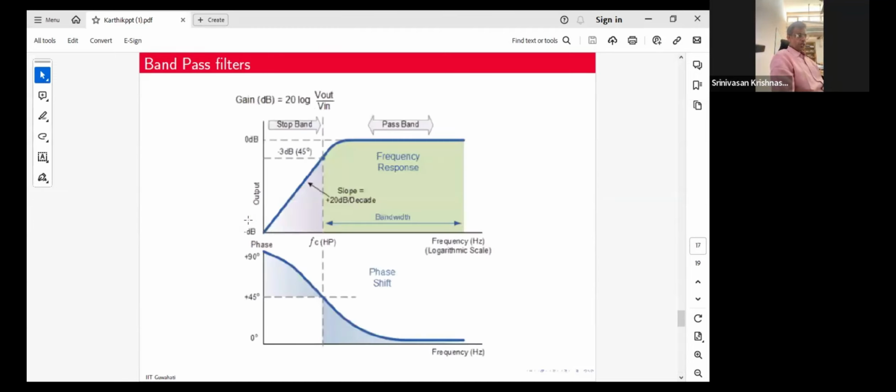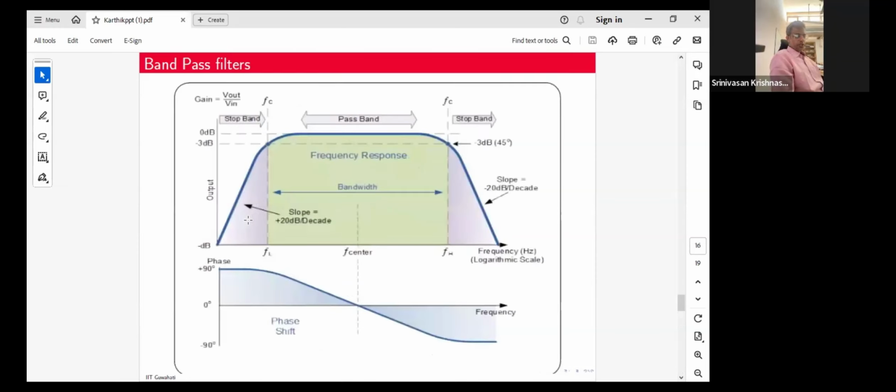The filters that you see here are all designed for continuous time signals. There are various transforms, such as the bilinear transformation, that you can use to convert an analog transfer function to a digital transfer function. This can be done fairly easily, and the digital transfer function will give you a relation between past outputs and current and past inputs that you need to implement to get the current output. That's how the DSP ultimately works. It's an equation that's there on a DSP processor.